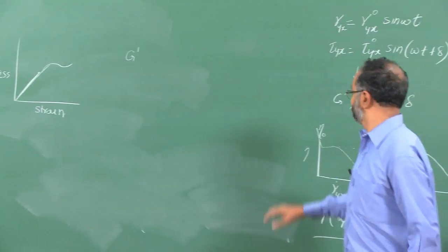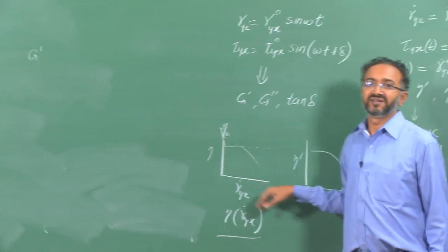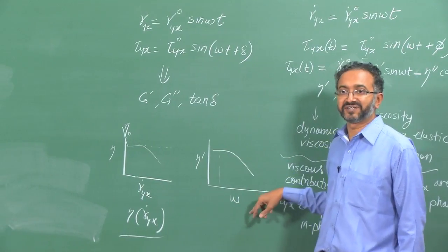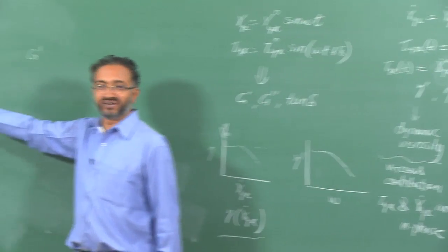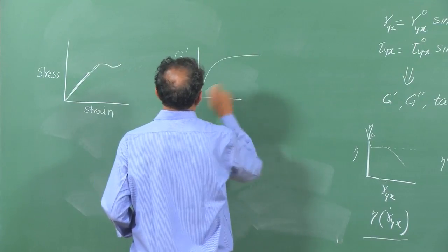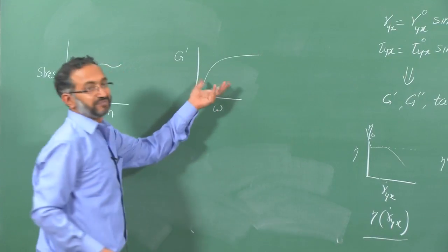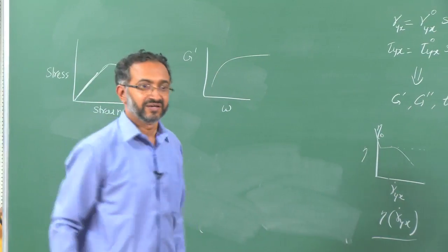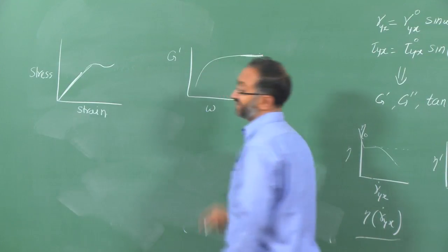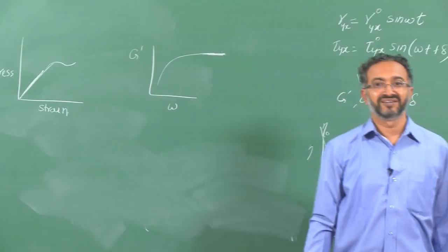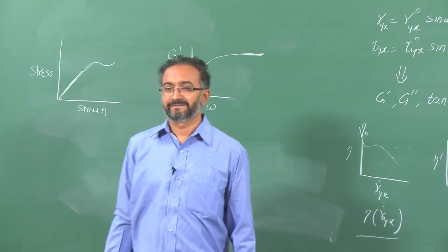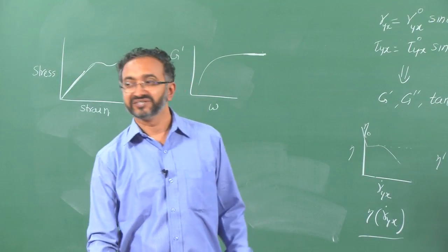In this case, this is a fluid test generally. This is something we are doing for a viscoelastic material, but looking at the viscous contribution of a viscoelastic material. This is a test which is done for solids, but we get some response like this. So, this is a test being done for viscoelastic materials. So, this G prime that we are getting, where the material is supposedly largely elastic only, will that be related to this modulus? That is the question.